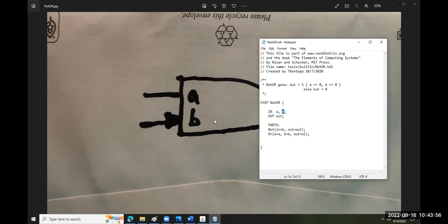And now the output, if I draw this out, if I explode this view and use a whiteboard like I just did, I'm going to have an intermediate step because I have output from the not that gets fed into the B of the or. So what am I going to put for out here? What's sitting in front of this not that you don't see? W1. The W1, correct. Does everybody understand what I'm saying? Should I show you the other picture again? No. Everybody get it? Okay.